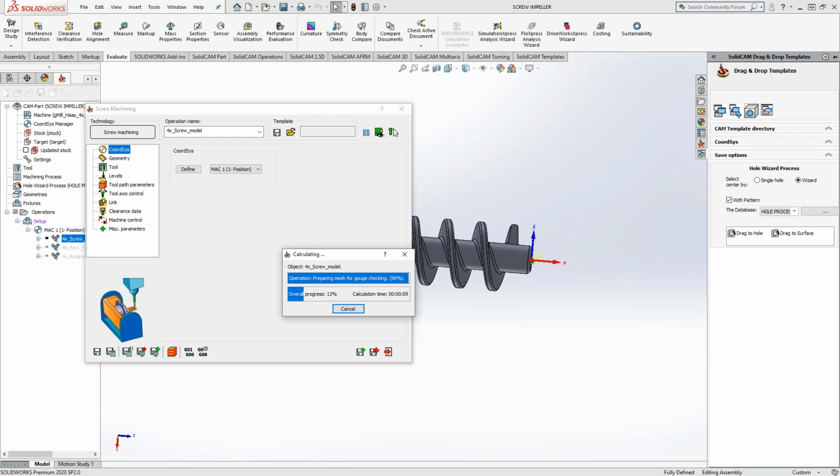Yep, absolutely. It's exactly what Kevin said. Whenever I'm training someone in the online sessions, I check to see if they are familiar with HSS, and if they're not, then we start with HSS because it is exactly the same. It's just that tool axis control section. And if you think about it, the angle of the tool is not really part of the toolpath. You're just kind of angling it to avoid collisions or anything like that. The actual control in a simultaneous 5-axis toolpath or HSS is the surface and that curve that you're staying parallel to, perpendicular to, or blending between.